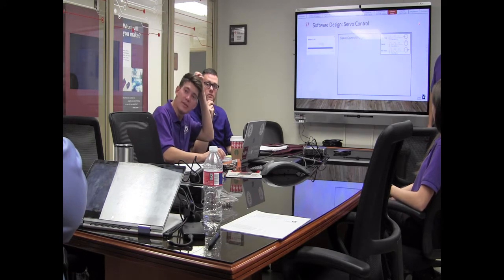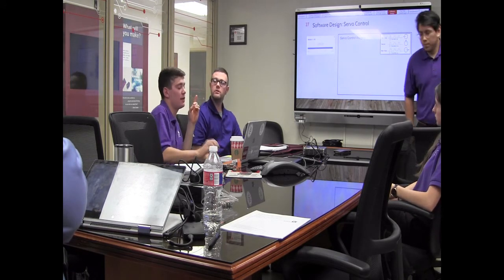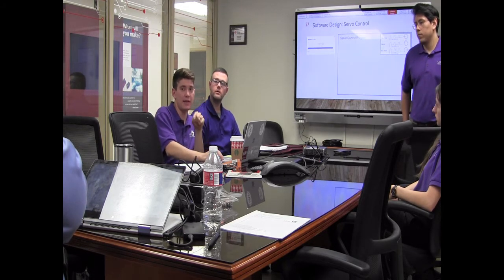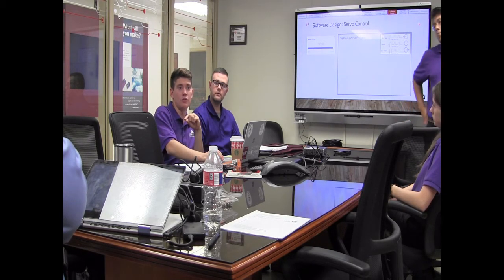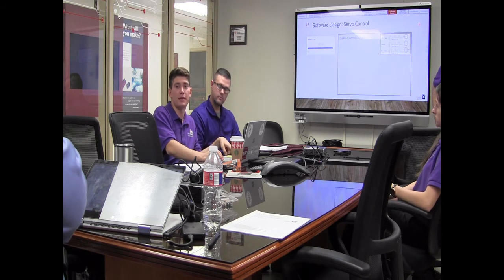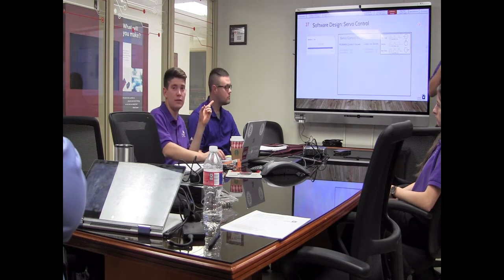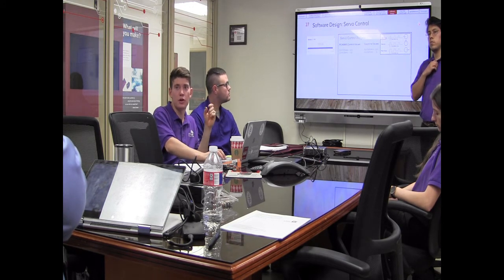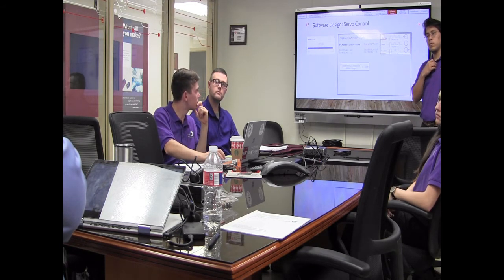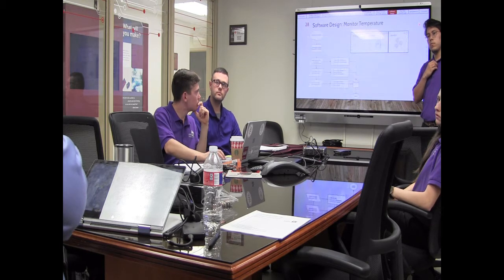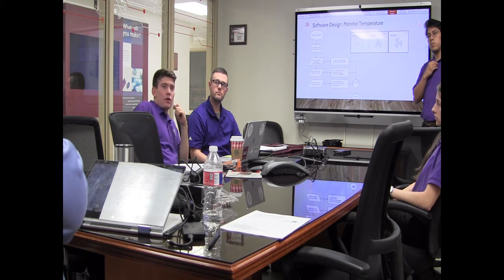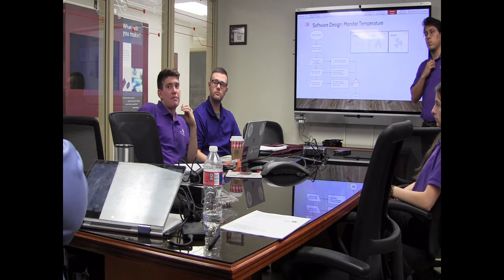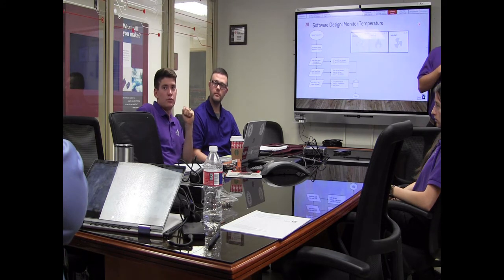There's a manual switch. So I ran into this problem in testing. You manually turn on the HVAC heat, and then you manually open the vent, and the manual overrides that logic of the 2 degrees over. So when you are heating, you are not exercising vent control? You're exercising manual vent control. Right. That's a good point.